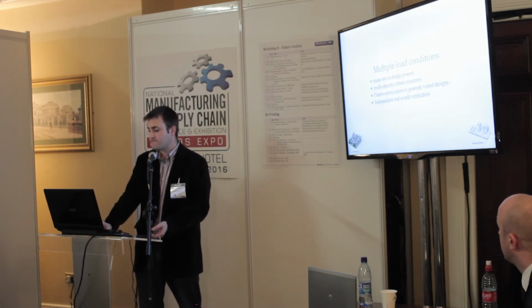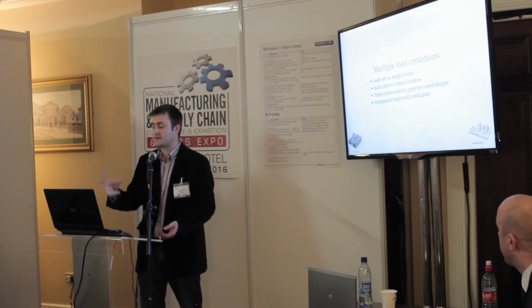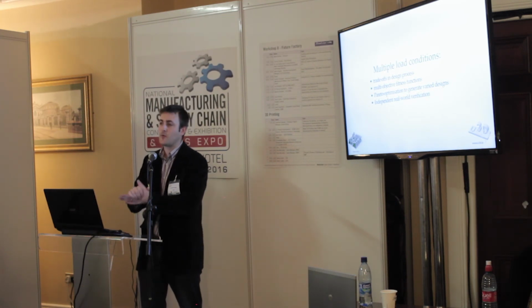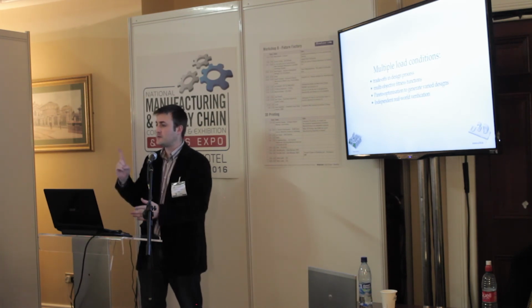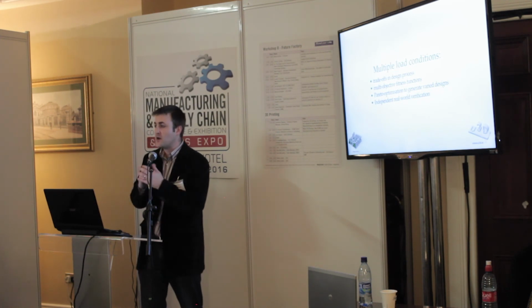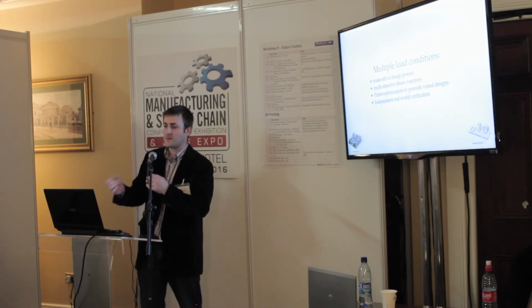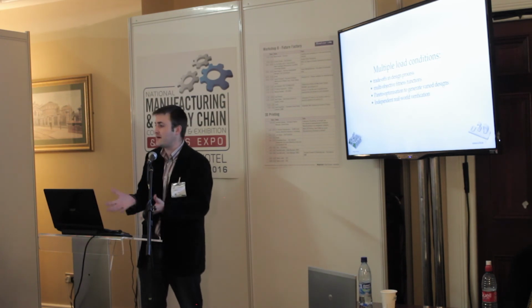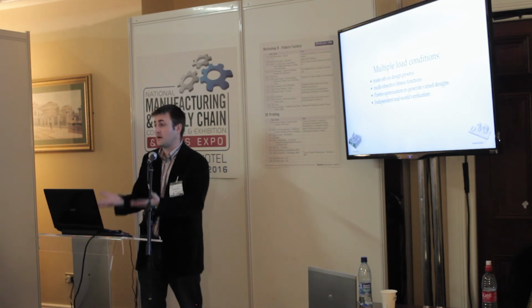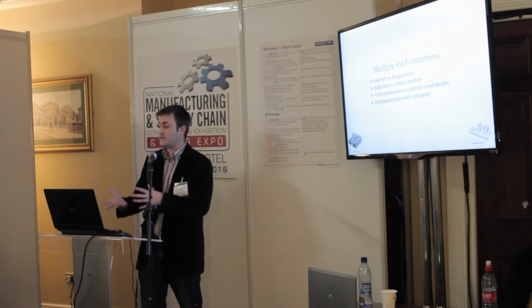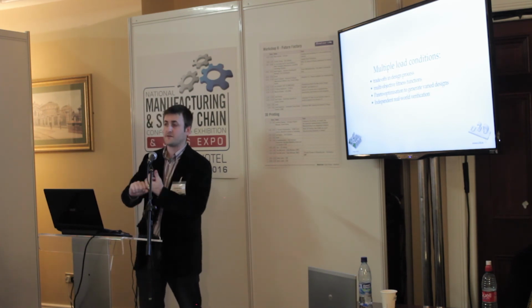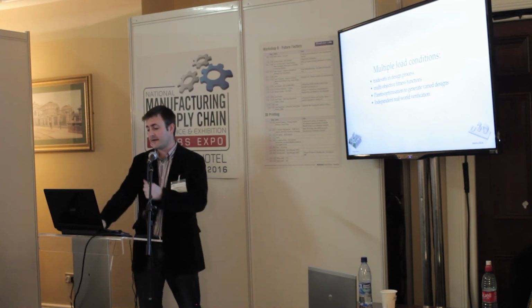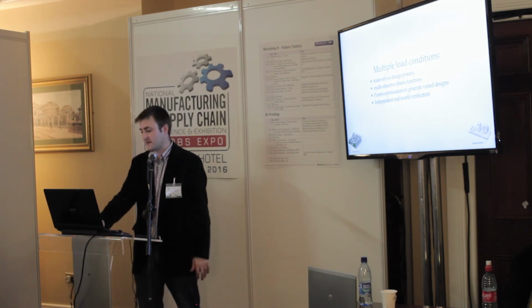Finally, multiple load conditions. This is another one. A lot of the work we see is for a single load condition. If you optimize a design for one load, then it will only react to that one load and nothing else. So if there's any sort of torsional forces or anything like that, it isn't evolved for that, it isn't optimized for that, and it will break. So you have to work out all the loading conditions that you need to design for so you can optimize it. We're working on approaches of Pareto optimization to see if we can generate better, more robust models.